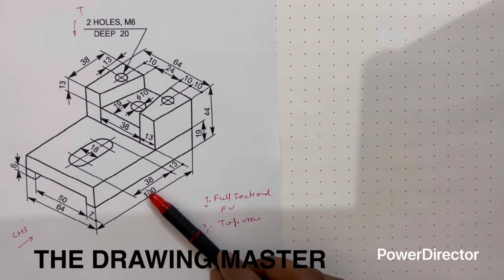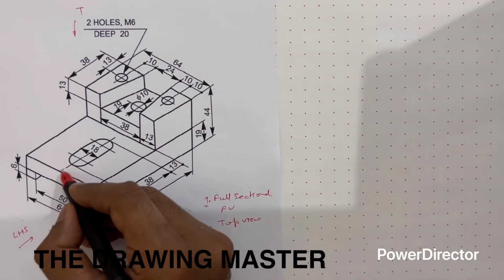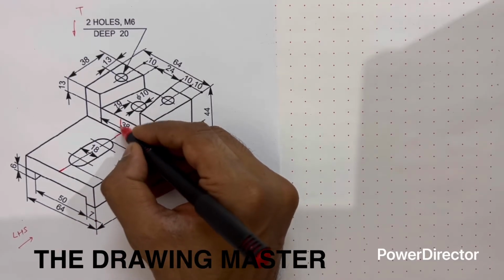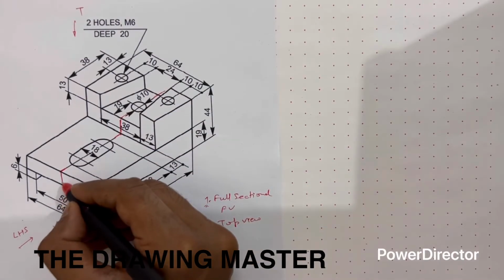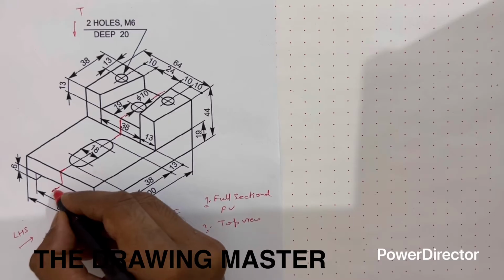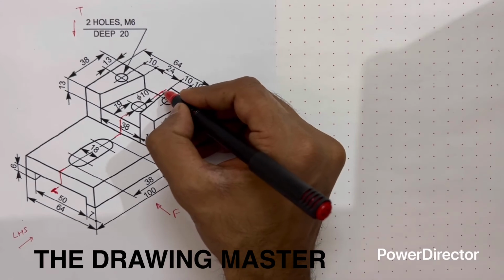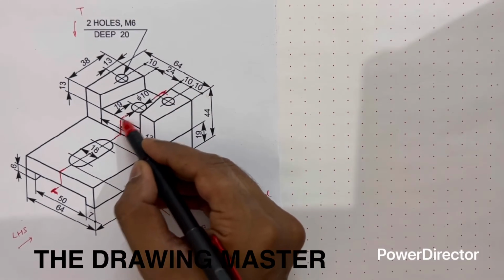This is the direction of view for front, but we want to see the sectional front. So we have to cut this object through this path. From here we have to section this object. Here is the cutting plane, a chain line with thick ends. It's not given to us, so we have to assume the cutting plane here. Through this path you have to section the object.